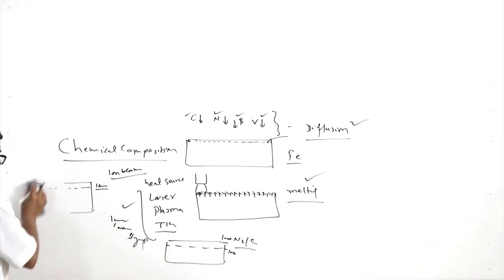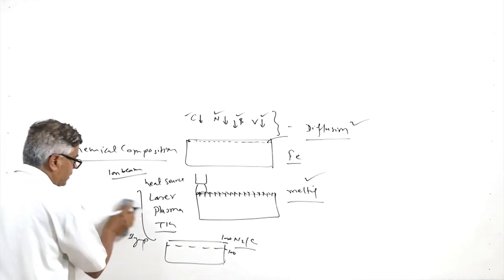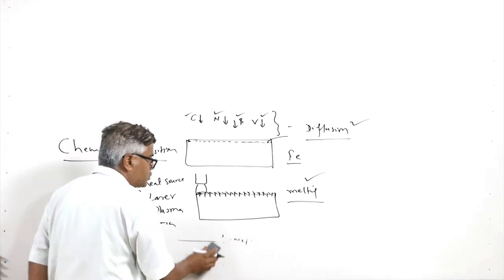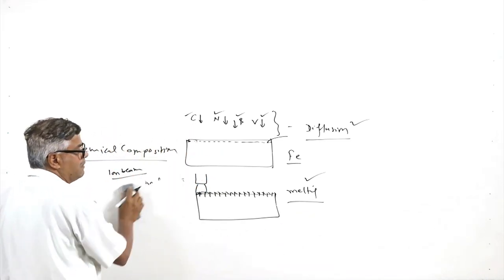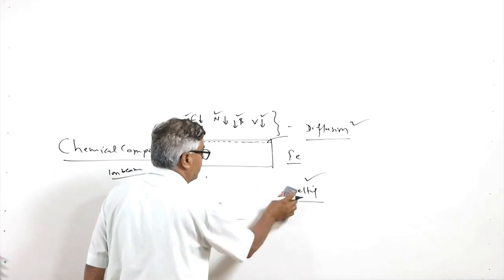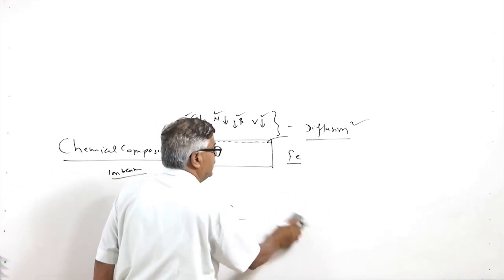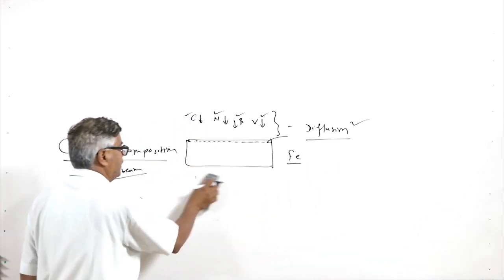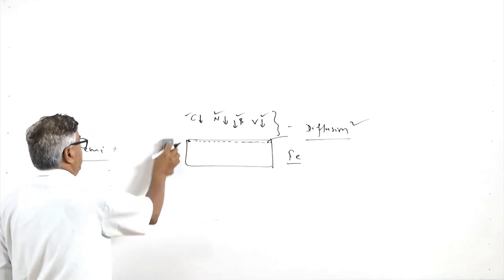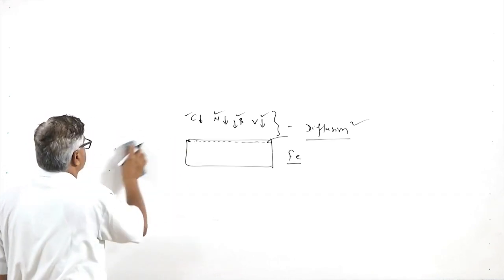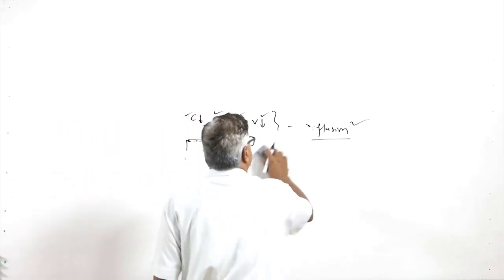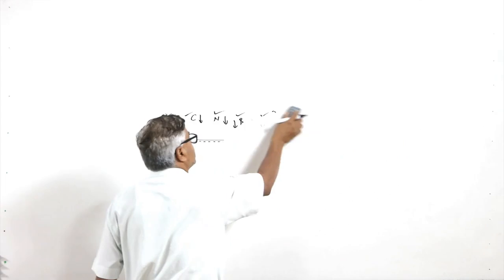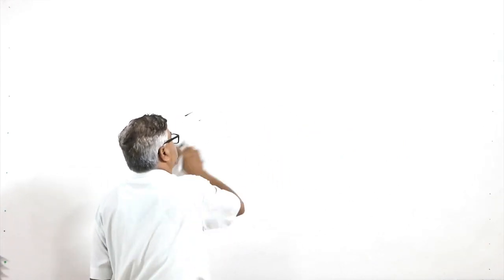So when the geometry is complex or the component is bulky, we need to use processes where differential heating and cooling is minimum. For that purpose, plasma assisted carburizing and nitriding are found useful, because the rise in temperature of the component is limited as compared to the conventional carburizing and nitriding processes.